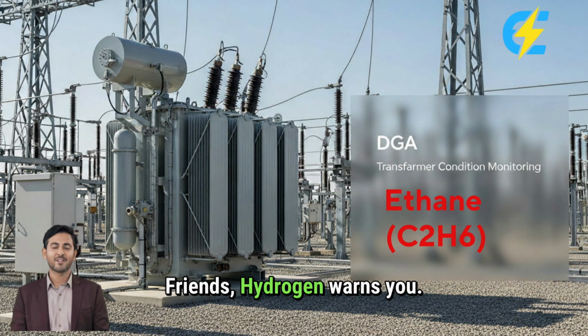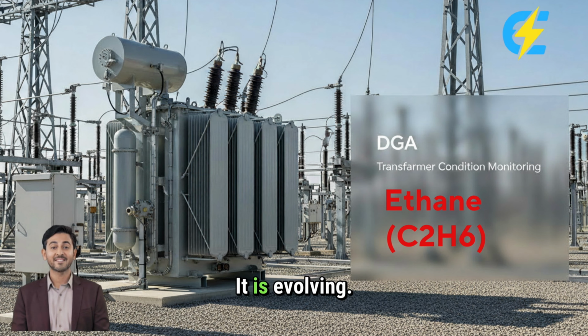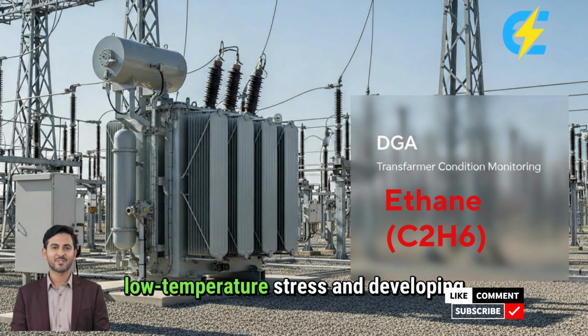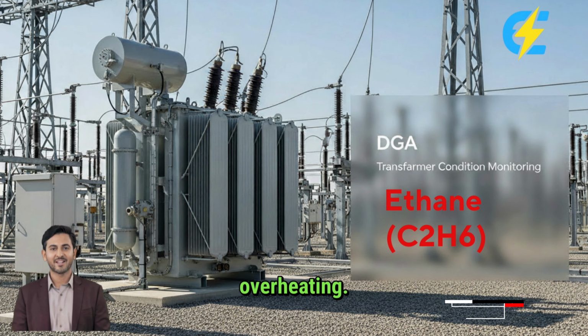Friends, hydrogen warns you. Methane guides you. But ethane tells you one critical truth. The fault is no longer just starting. It is evolving. Ethane is called the transition gas because it sits exactly between low temperature stress and developing overheating.